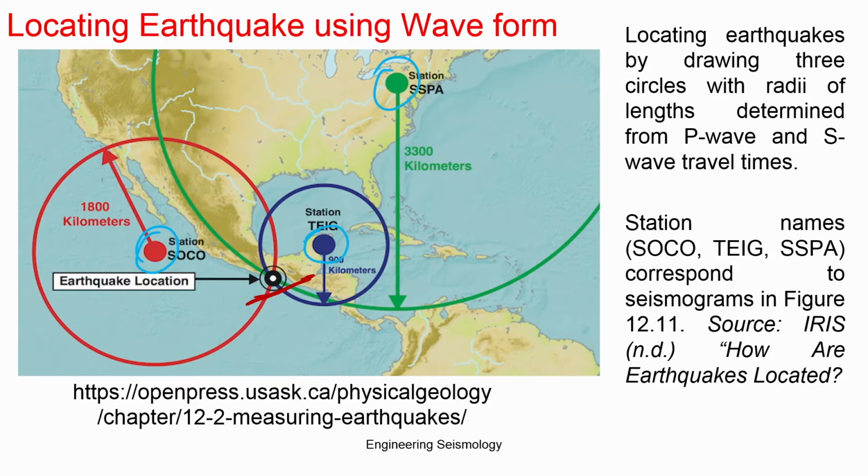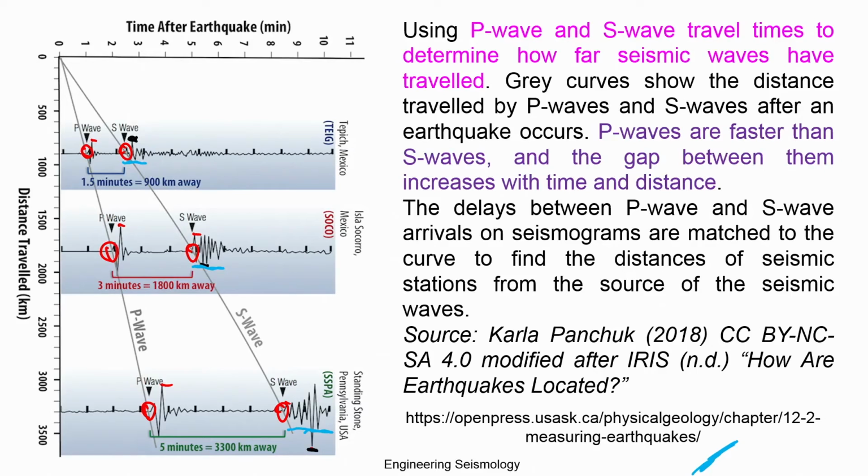Last class I drew it freehand and explained that. This class I have shown you how the waveform differs. If you have to find an epicenter, you need three records and you have to pick the P wave arrival very clearly, like what we have given here. Then the travel time will be taken and then you can know. In the physical case, you use the time of arrival and the velocity in the region to estimate a distance.